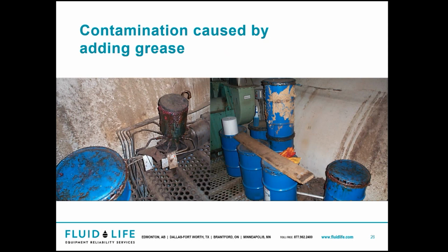So seeing something like this here, we have 1, 2, 3, 4, 5, 6, 7 totes of cans of grease here. Now, this here is the oldest. We looked at all the labels, so the first problem here is first in, first out. Use your oldest stuff first. That allows us to properly cycle our lubricants.